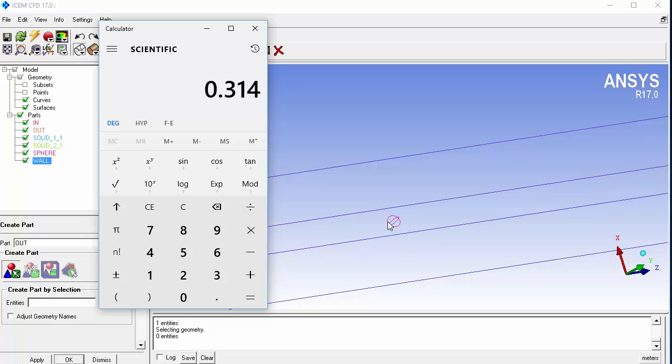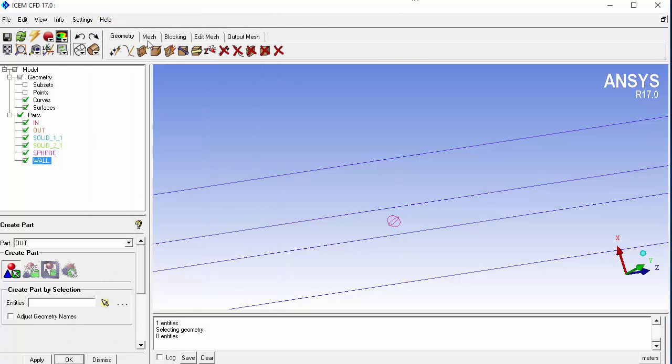And with high resolution, we can even properly solve the flow field and flow features along this. So I propose that on the whole sphere, we can start with around 80 nodes around the sphere. So the size is going to be 0.004.